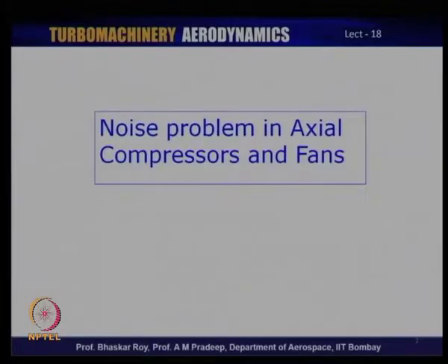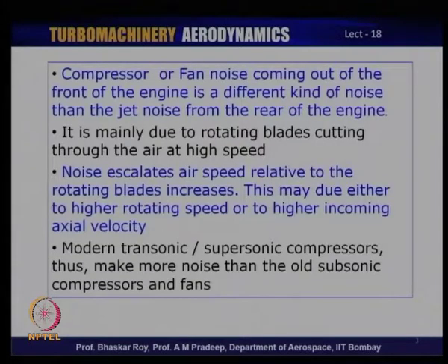We are looking at noise problems in axial flow compressors and fans. Now, compressor or fan noise, as I mentioned, is a different kind of noise than jet engine noise. The jet engine creates a heavy noise that is due to the shearing action of the jet coming out from behind the nozzle of the engine, whereas the noise created by the compressors or fan is mainly due to the rotating blades cutting through the air at high speed.